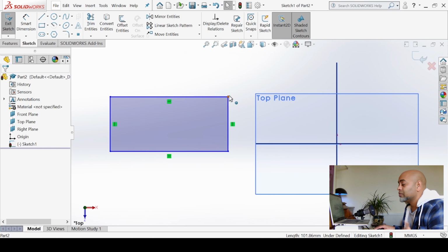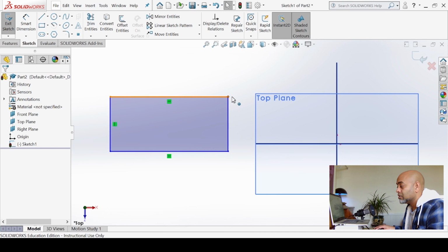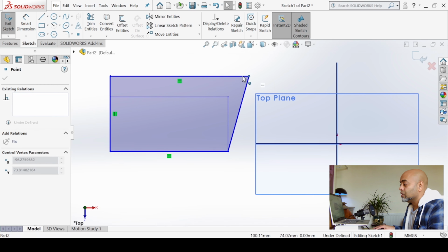For example, this rectangle came out of the box and picked those constraints for me. That's exactly what I wanted. However, if I didn't have that shape in mind, I can let go of some of these constraints. I can delete that little indicator just by clicking and deleting from the keyboard. So that is gone. Let's have a look at what it does now. Look at that motion now.